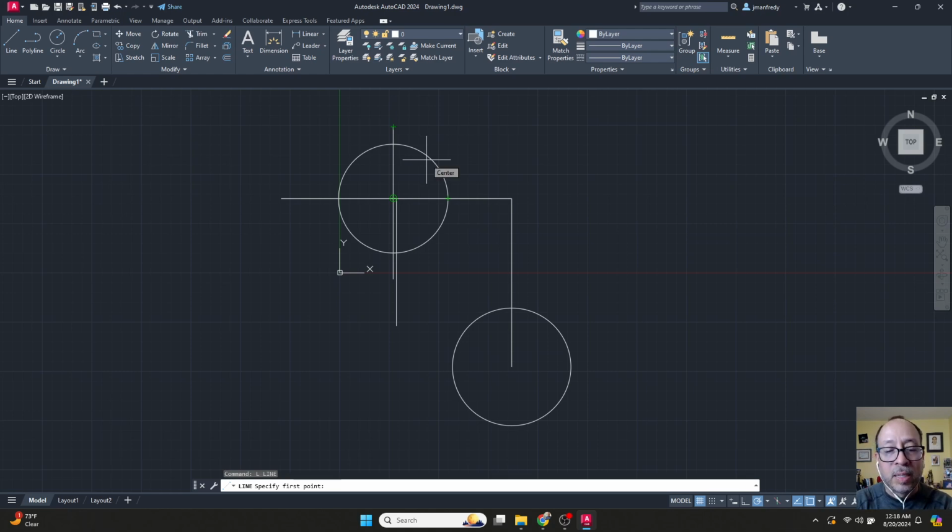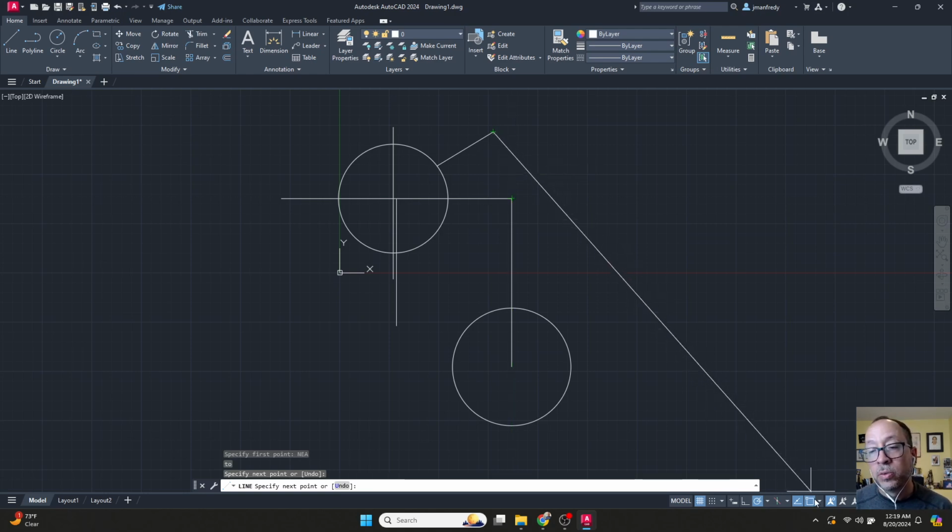So in the middle of this command, I can type NEA, the first three letters, enter, and it'll basically let me snap anywhere near my mouse location. Here, here, here, anywhere. Click, and it'll snap there perfectly. And then obviously, after you've done the work, it goes back to the usual O snaps that are currently active, the ones with the check marks. Hit escape. And that's a quick tour of the O snap command.